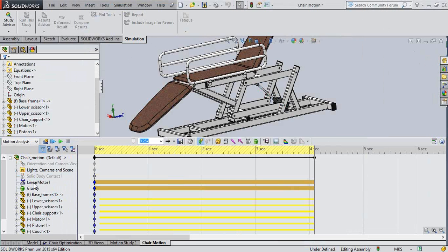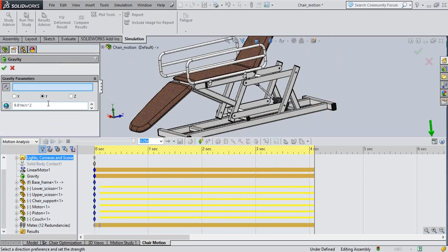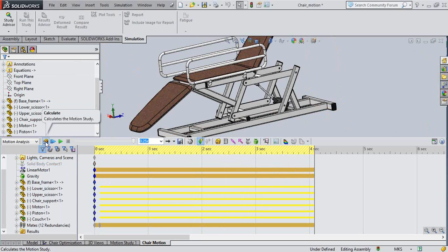Then I have to set the time phase of the event to happen, because it is time based motion. So I'm now selecting a time of 4.1 seconds, and I'm taking an effect of gravity in the y direction. You can see down there in my negative y direction, which is appearing in the window in the green color. And I just click OK, and I just click calculate.